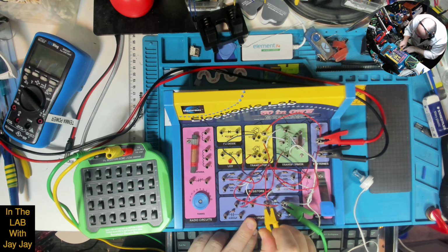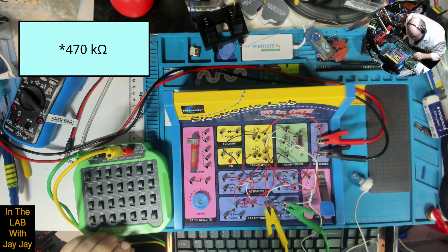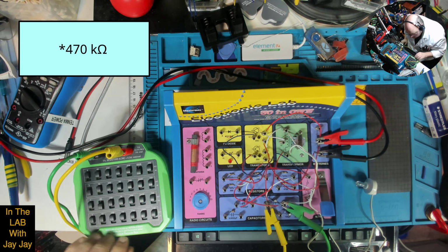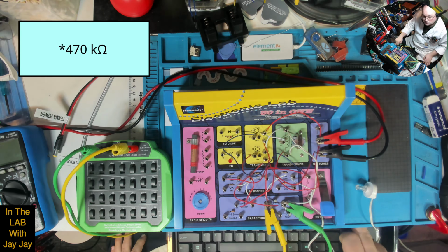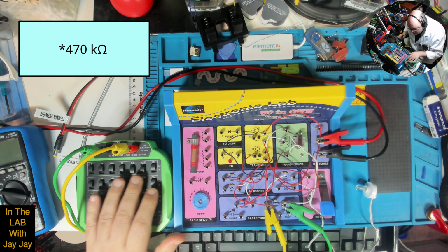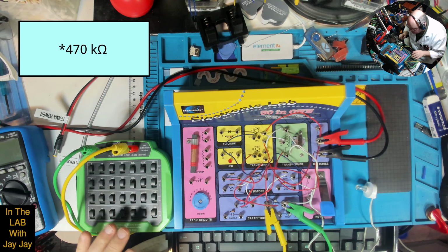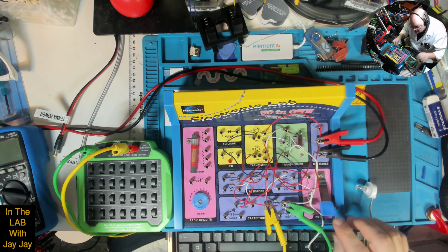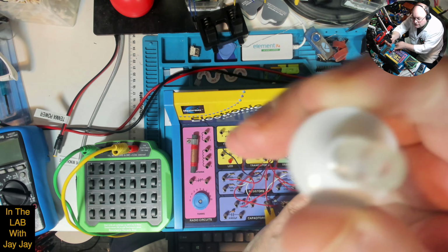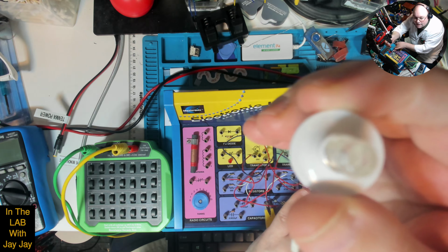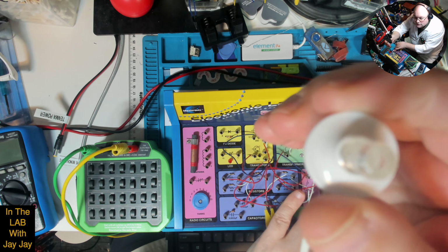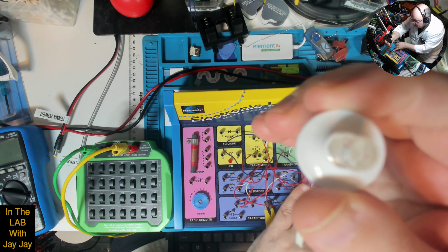Now, if we put this in at 470k, so let's say, just 1 second. All right, so I've got the resistor here set at 400k plus 40k plus 30k, 470k, and it's hooked on here. So when we power it on and we press the button, it should start to oscillate, which you might be able to hear through the headphone on the microphone. We'll see how this works after we pre-process everything.